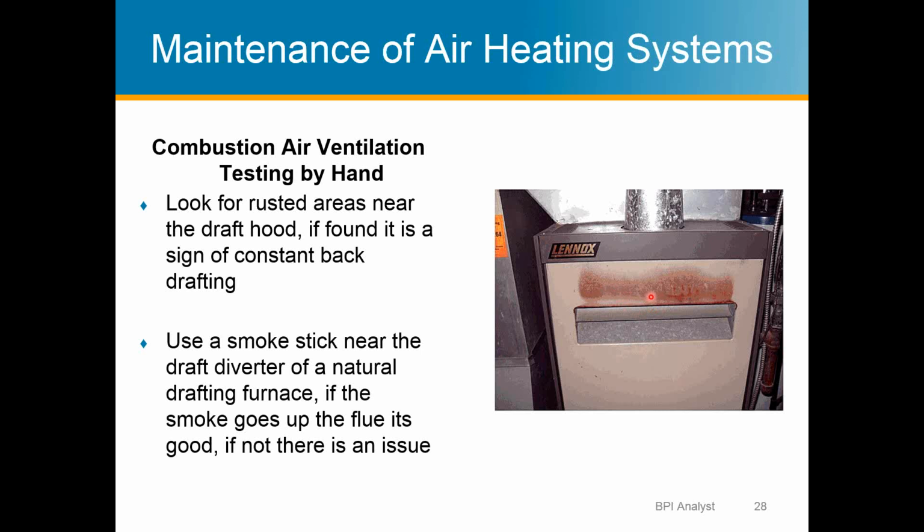That rust is from, we talked about condensing furnaces and that the water vapor is corrosive. Well, that's what's happening. If some exhaust gases are spilling out, it gets on this metal, which, if the heaters weren't on, means it's cold outside. So the metal's cold, just like a can of soda on your desk.